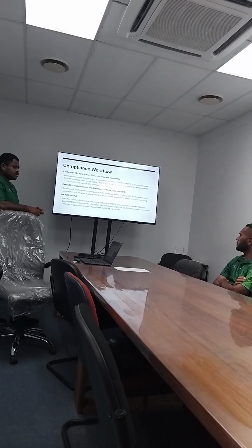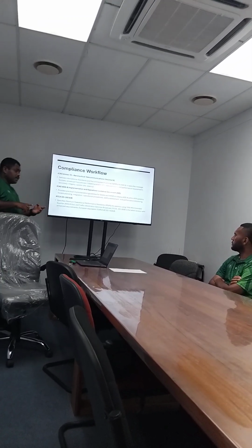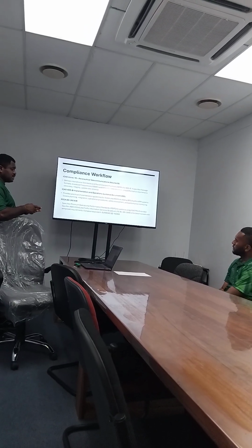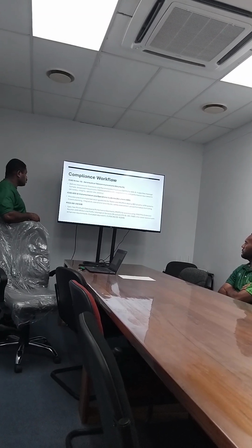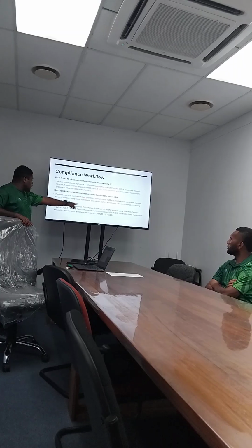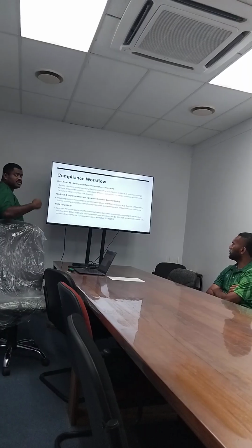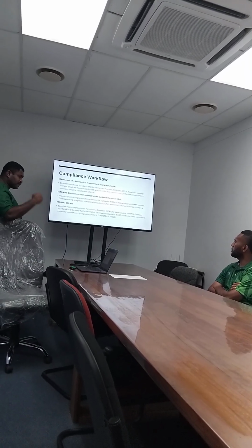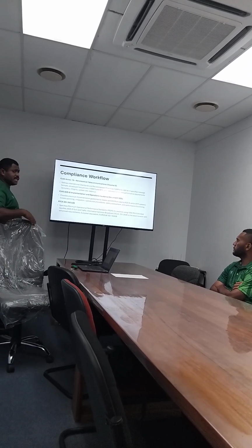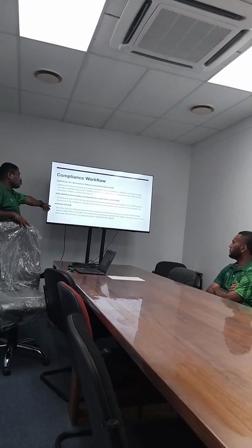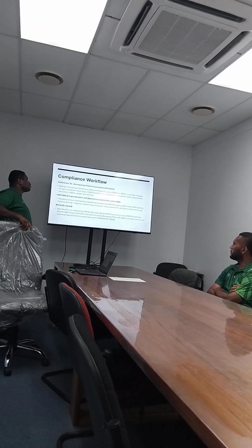Now we need the aircraft type, velocity, the ICAO address, and position. If you do not have ADSB extended squitter, which we usually call Mode S, then you are not allowed to fly in the non-radar FIR. It's mandated by CAF. Any aircraft flying within the non-radar FIR has to be equipped with ADSB extended squitter. If it's not, you won't be able to fly.